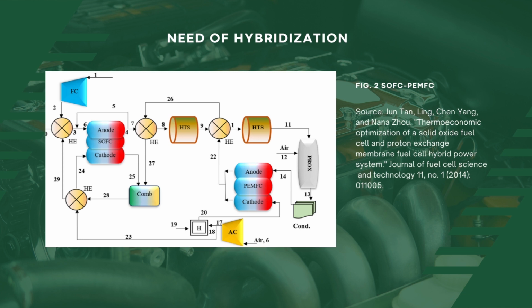Some of the unused fuel is cooled and again passed through a high temperature water gas shift reaction and then through a low temperature water gas shift reaction. These two processes can cut down carbon monoxide significantly and the condenser receives hydrogen-rich fuel.